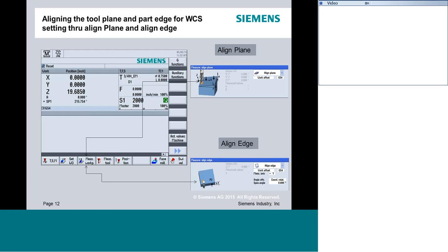it mimicked where the CAD/CAM package thought it was going to be in space. Now these high-end machines, like the Siemens Control, have capabilities built into them where they can manage that. So from the CAD/CAM system, if you are posting from CAD/CAM or programming at the control, you only have to be worried about tool movement. You never have to be concerned with what the machine really has to do to get the part there or get the tool there. You just forget the machine even exists for the most part and concentrate on where the tool is going around the part.